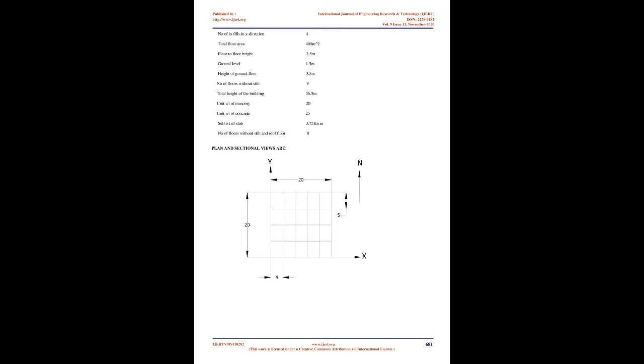General. The Bhuj earthquake occurred in 2001 and caused extensive damage to structures and a huge loss of lives. The collapse of more than 100 reinforced concrete buildings was due to the open ground story, that is, the soft story. The Bhuj earthquake has emphasized that such buildings are extremely vulnerable under earthquake shaking. Significant doubts have arisen in the minds of professionals in dealing with these structures, and in how to make the structure more stiff to resist earthquakes.